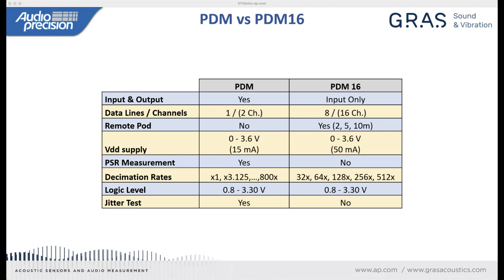The PDM line driver sort of boosts the signal and makes up for the ability to drive a capacitive load that you see in some PDM microphones. Unfortunately, you do still see ringing and other artifacts from impedance mismatches and other long cable issues when you use a PDM line driver that don't occur with the PDM16's remote pod.